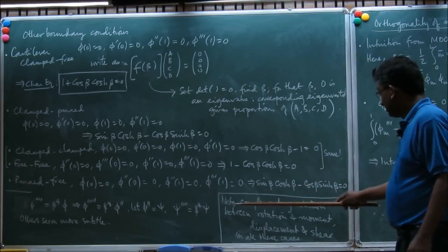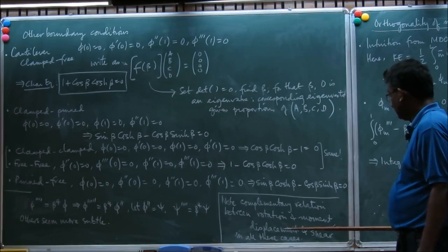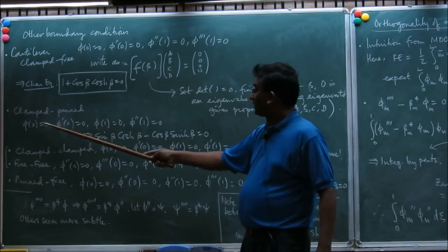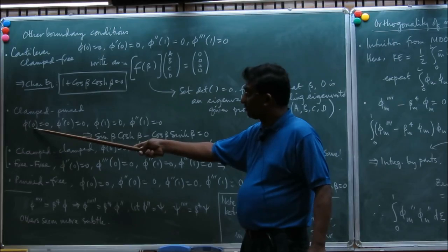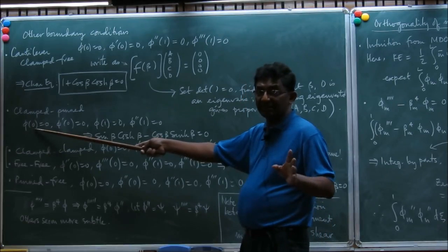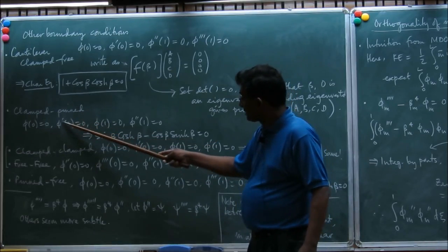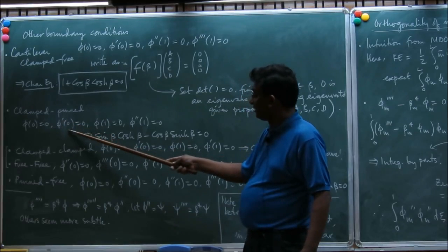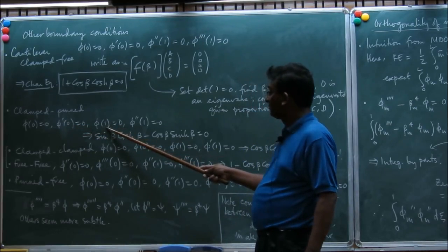There is something else that I would like you to see, the complementary relation between rotation and moment, and displacement and shear. Over here, the displacement is 0, therefore the shear, we are not saying that it is 0, the shear can be anything. Over here the rotation is 0, so the moment can be anything. Over here the displacement is 0, so the shear can be anything.